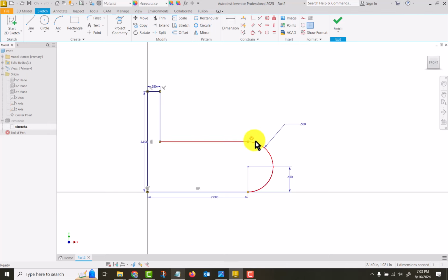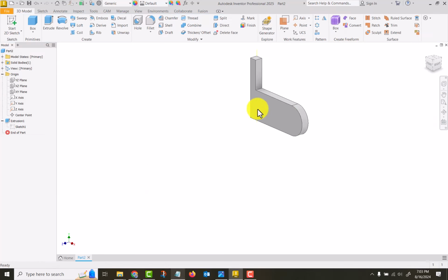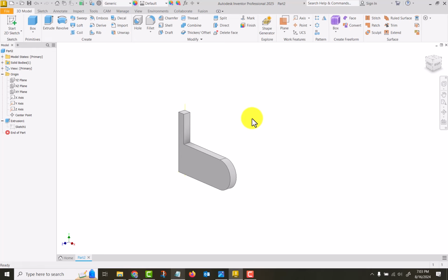Okay, we've got tangent there. That's horizontal. I put this dimension in, so that forced it to be tangent down here. So let's add a perpendicular constraint to these two. Oh, it didn't click. There we go. And now we're fully constrained. I can finish, and you see it automatically updates the model. Okay, let me pause this video and then come back with another.